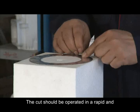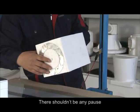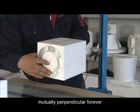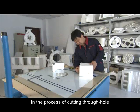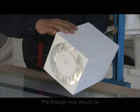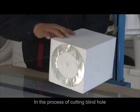The cut should be operated at a rapid and constant speed in one pass. There shouldn't be any pause, and the model and the resistance wire should always be mutually perpendicular. In the process of cutting a through hole, the resistance wire threads the white foam adjoining the model. The through hole should be controlled within 20 mm.